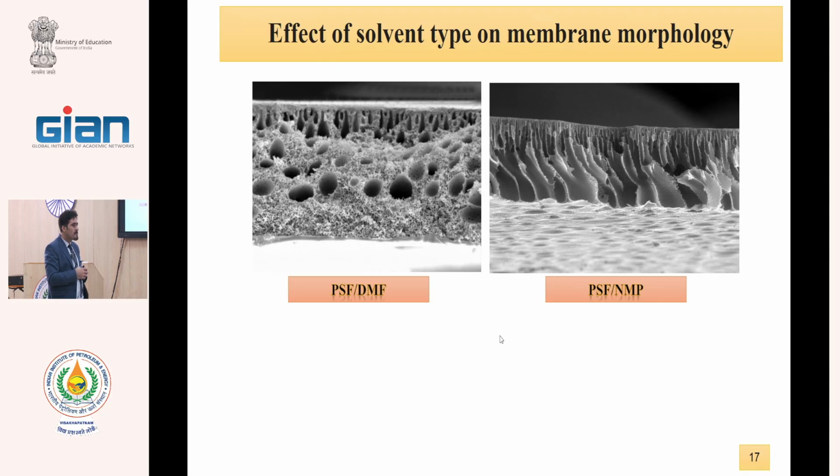Sir, actually I have used YSZ, yttrium stabilized zirconia, over which I have cast nickel oxide. But I faced that my tapes were broken. There were cracks over the tapes. Yttrium stabilized zirconia was the main support over which I cast nickel oxide. But I have seen that there were some cracks over the nickel oxide. My tapes were spoiled.